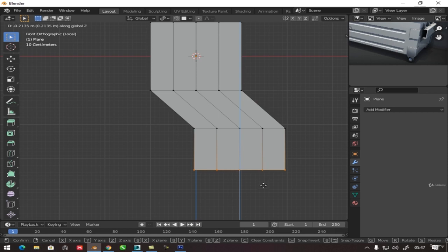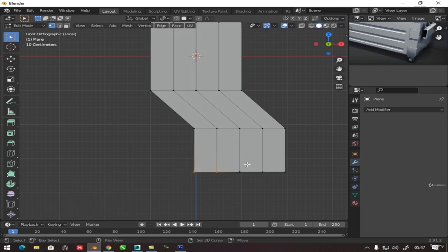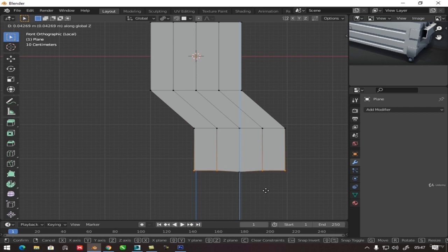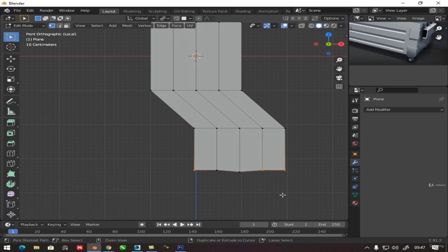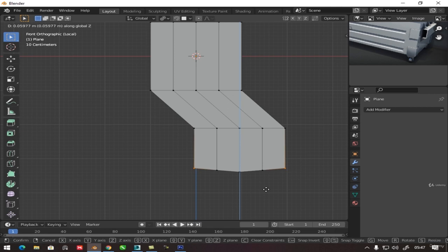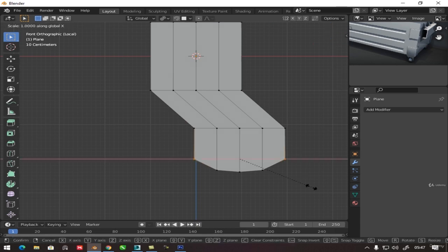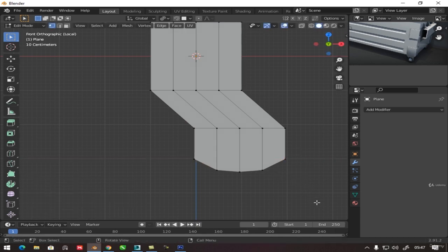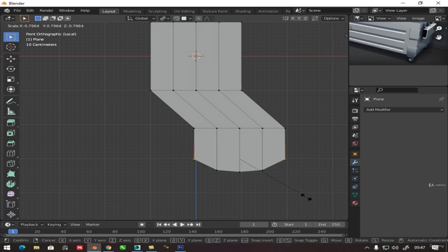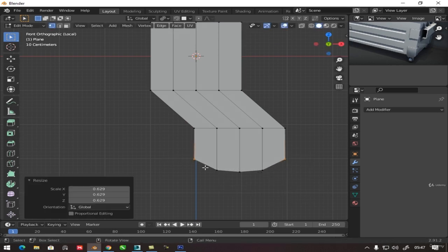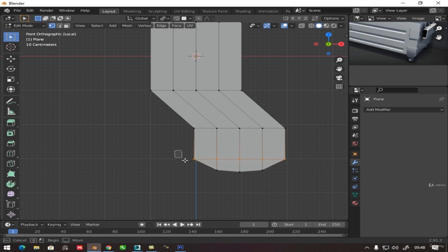Making this shape here. Now I get this tool. Let me go back here, a little down. Now get these 4, G, Z, I bring slightly. Deselect this with the Ctrl, G, Z, bring it to here to give it a little round and hit this part. Now this too, I can press G, X, or just S. It won't change, so I'm giving a connect with those, so I press J, and it does this junction here.